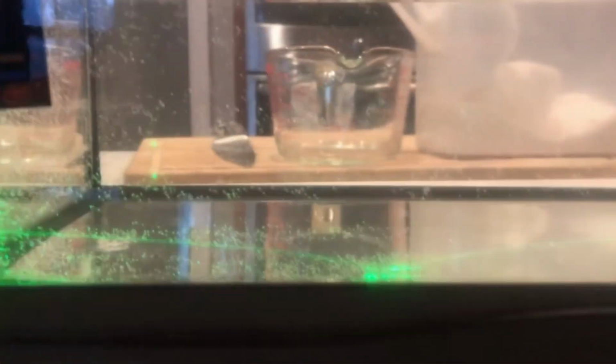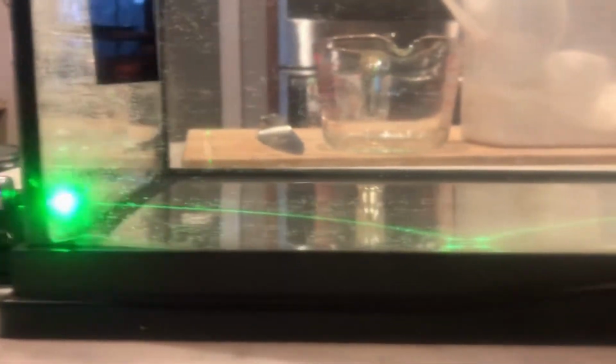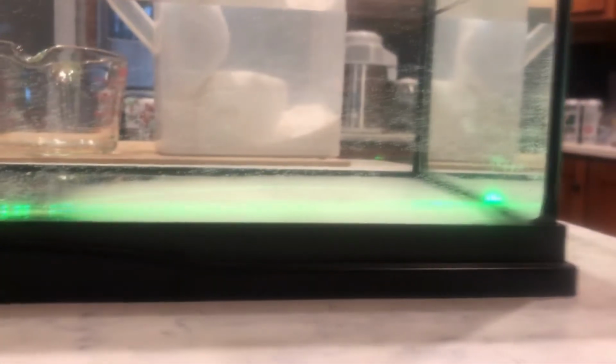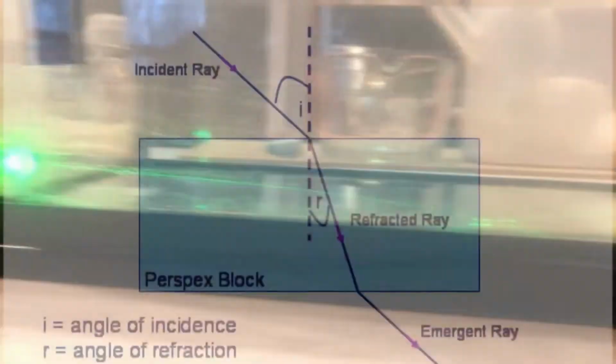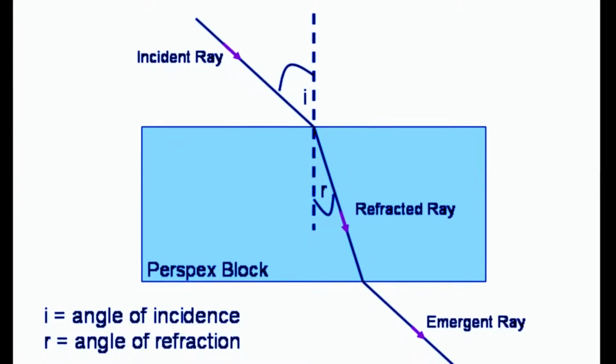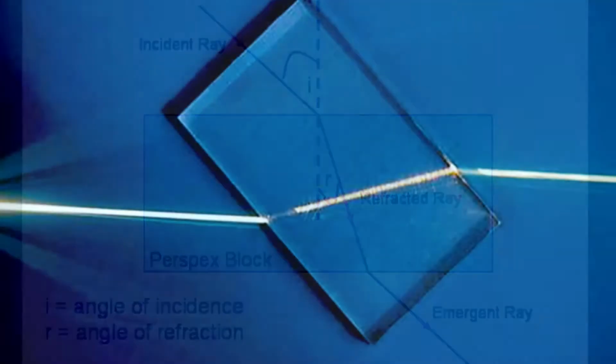The light beam changes direction when crossing different optical density mediums, such as warmer or more humid air. This apparent bending of the light beam is always in the direction of higher optical density, which is defined by the refractive index of the medium. Refraction only takes place on the border between two different optical densities. No refraction occurs unless the path of the light crosses a boundary to another layer with a different refractive index.